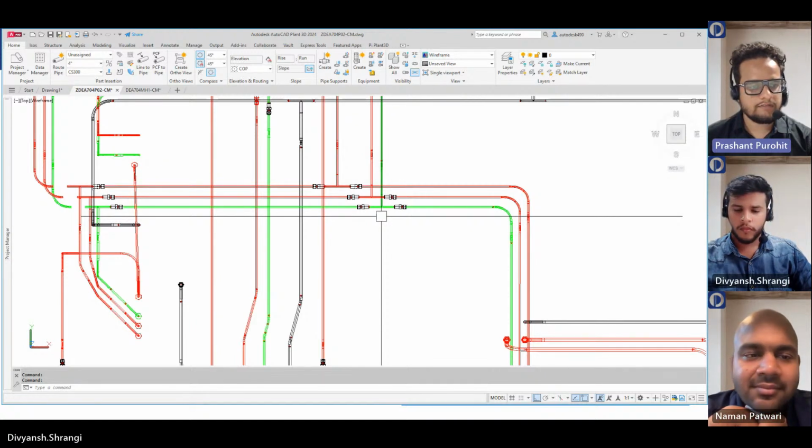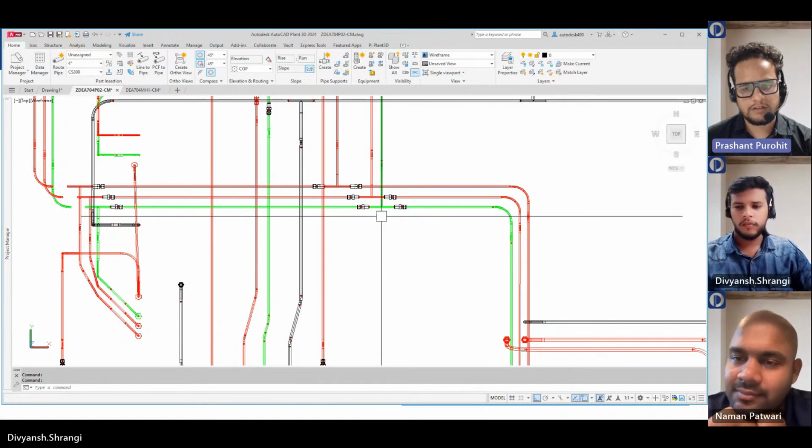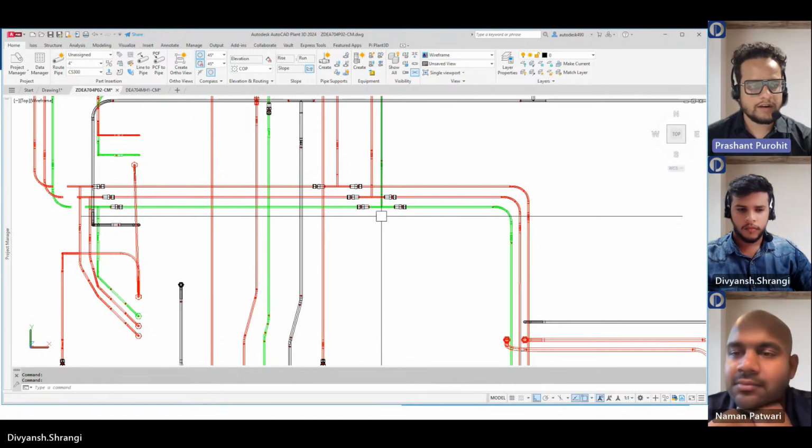So it is really very helpful. And again, it can be used in other projects as well, because when you are viewing anything in the Navisworks platform, you cannot see the welds directly because they are inside the pipe, or they are the connection points. So if you want to see where my field welds are, where my shop welds are, where my coax welds are, if there are any, then this method is really helpful to provide weld spheres over them. And we can also remove them in a single click.